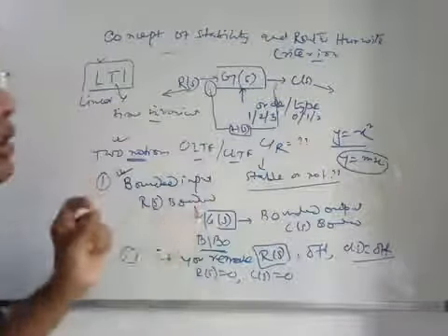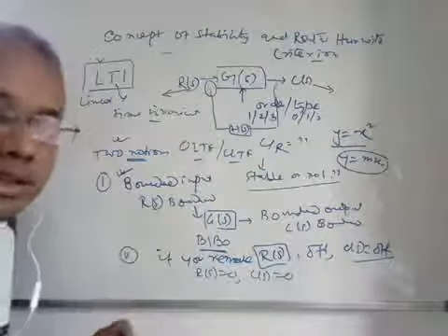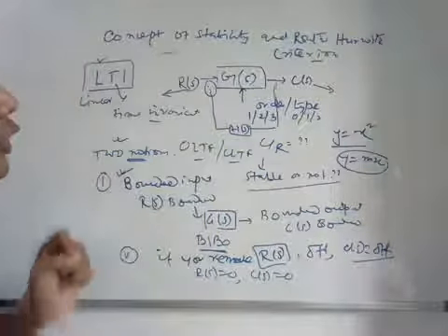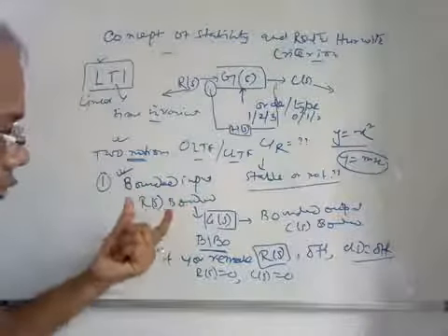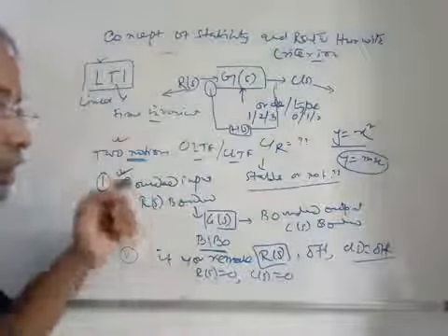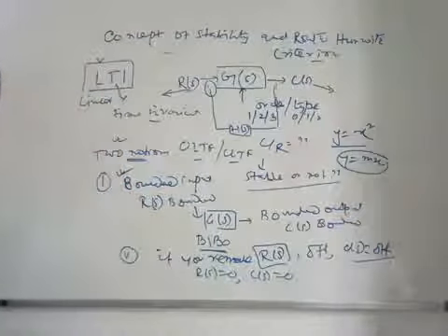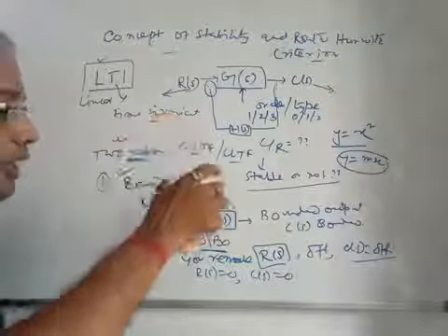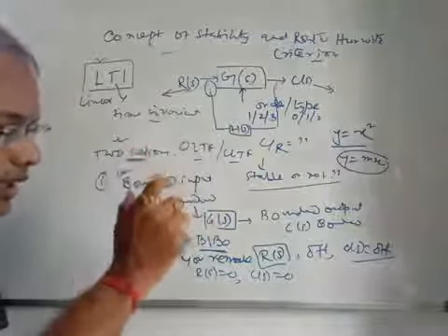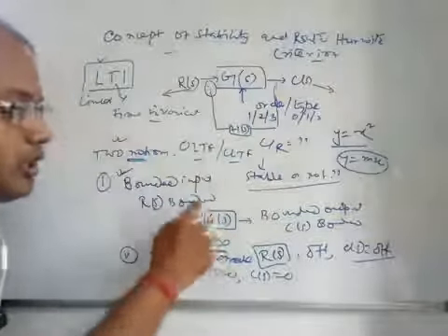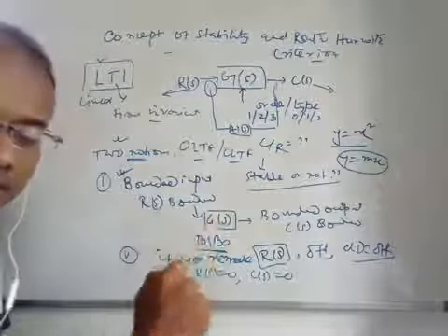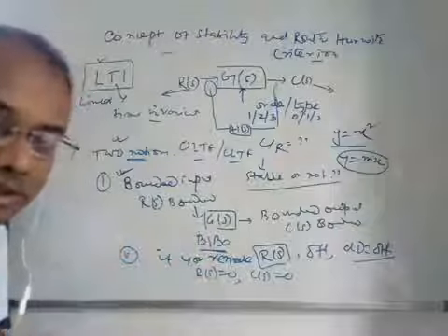So we will concentrate our analysis on linear systems. Okay, but we have called it bounded input, bounded output system stability, right? So I will just give you some analysis of how this bounded input, bounded output stability gives the relationship with the pole locations of this G(s), that means your transfer function, right?